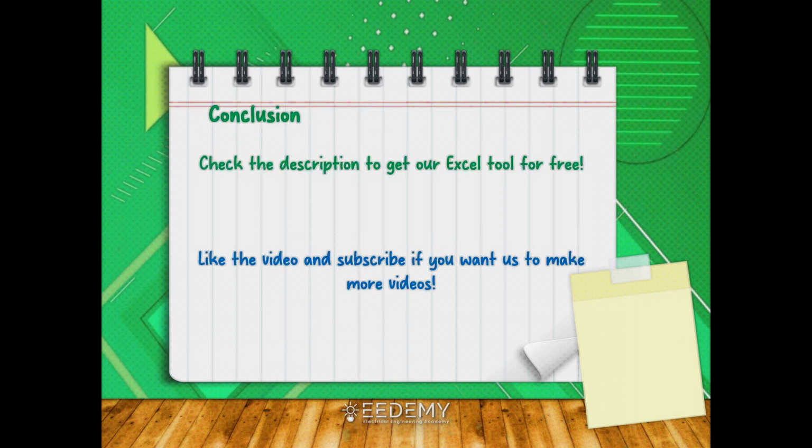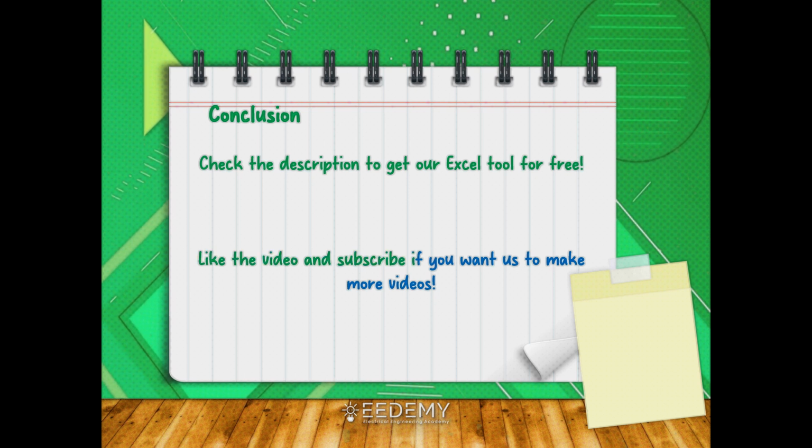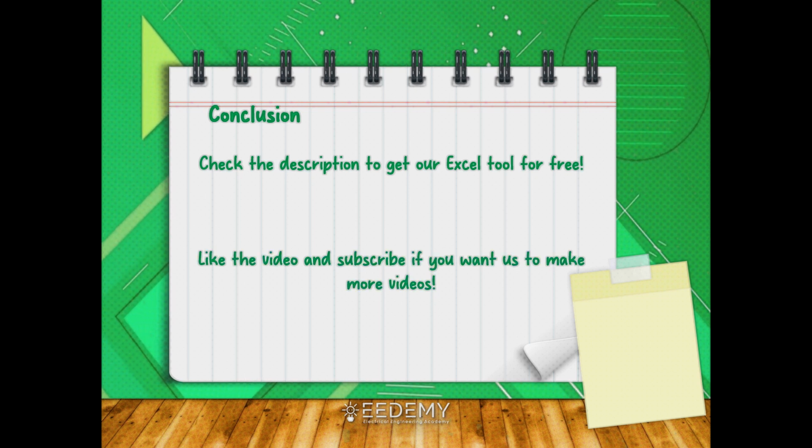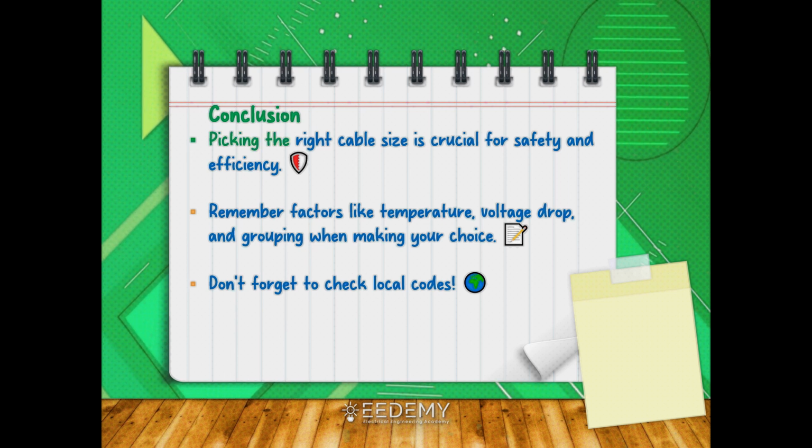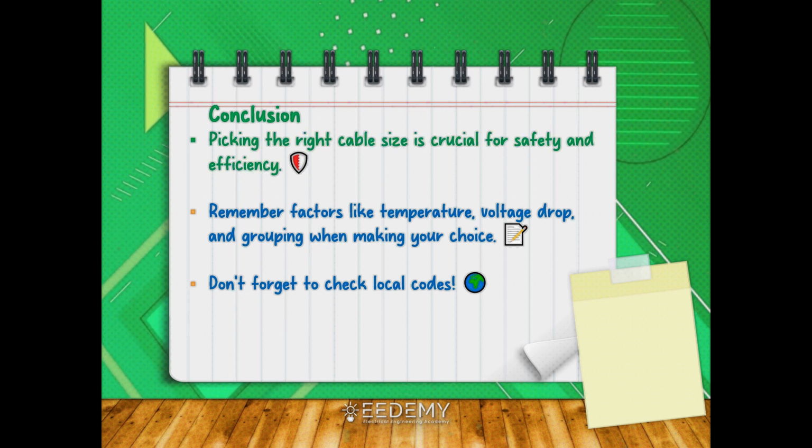Conclusion: getting cable sizing right ensures safety and efficiency. Just remember, consider temperature, grouping, voltage drop, and short circuit capacity. Oh, and don't forget to check your local codes and regulations, and maybe keep a multimeter handy for the adventurous electrician.